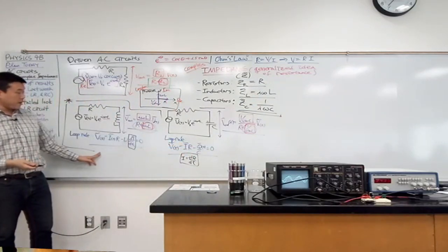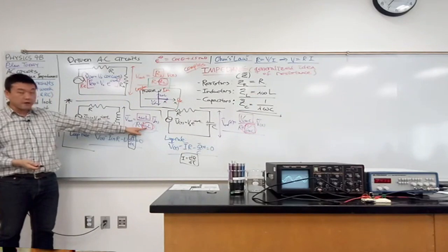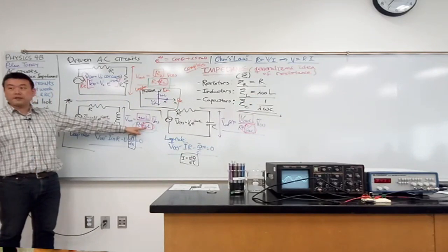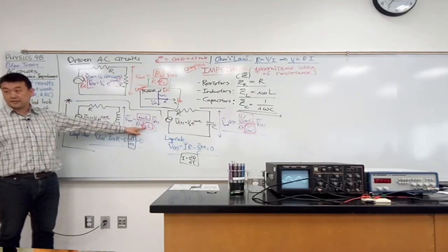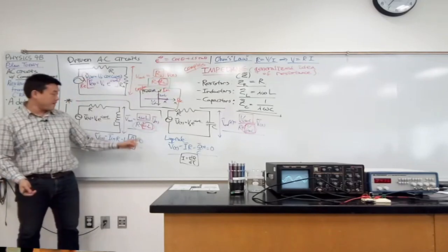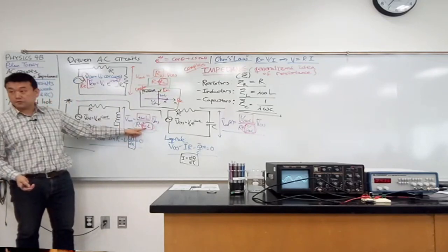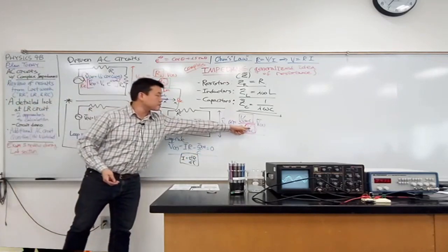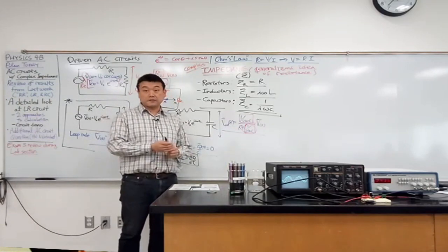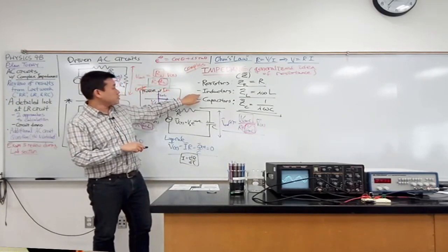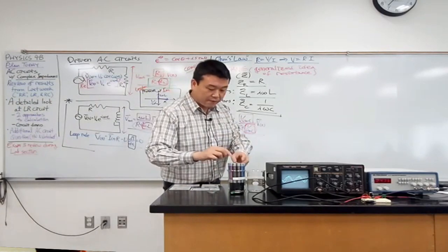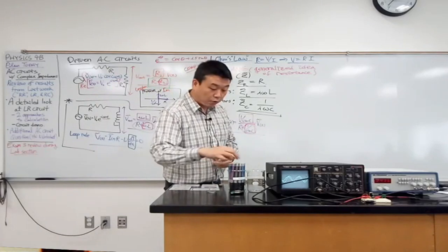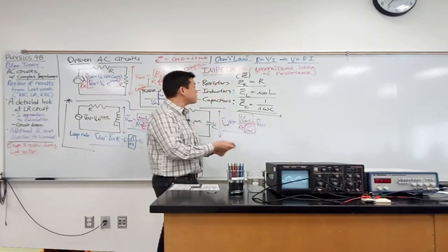When you go through the calculation, you identify this term, which if you could call it resistance, everything would work out so nicely. So you call it impedance, and identify this with the impedance of the inductor, and identify this with the impedance of the capacitor. So with this introduction of impedance, this is what we can now say, and this is the whole reason for introducing impedance.